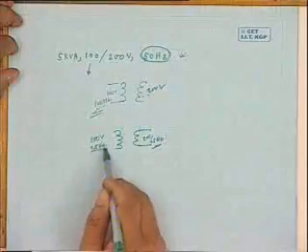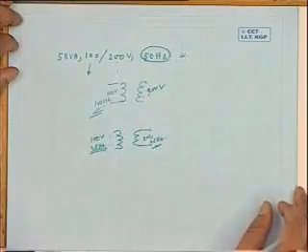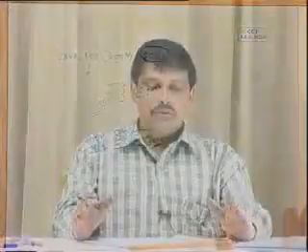Why is it so? You remember that if you operate the transformer at a reduced frequency, what will be the level of flux with respect to the rated condition? Suppose with 50 hertz and 100 volts applied, whatever flux is developed inside the core, let me call it the rated flux.